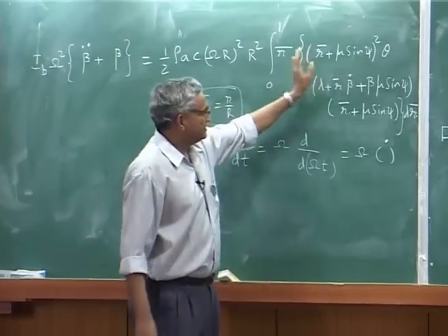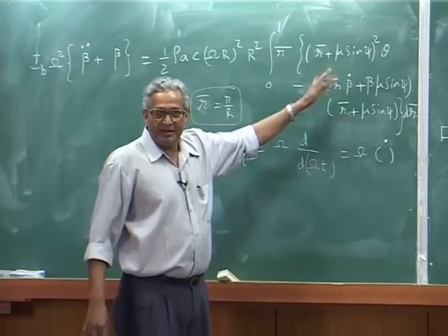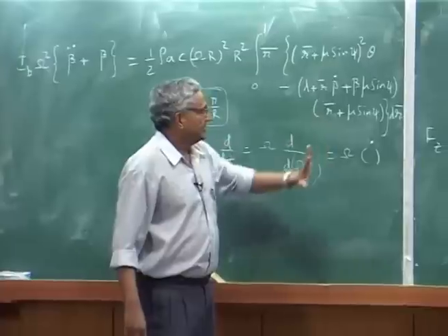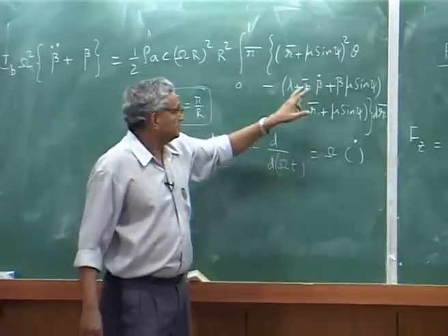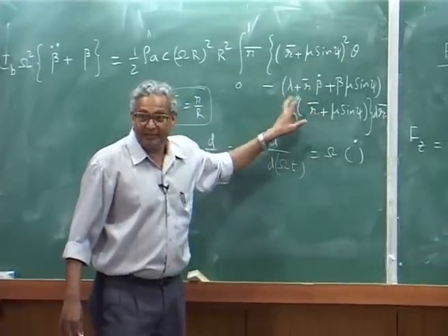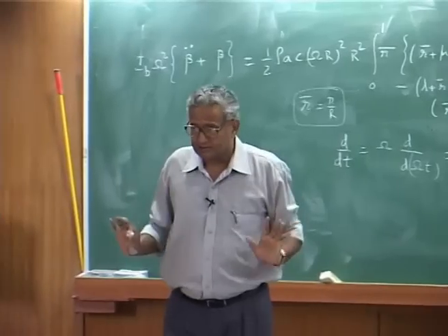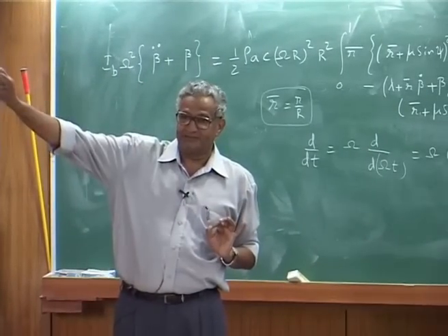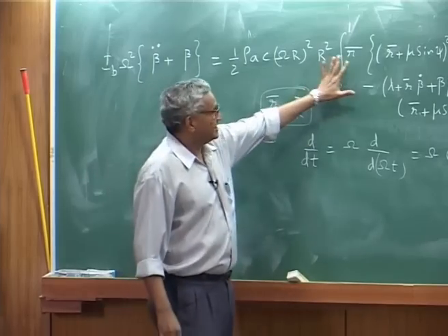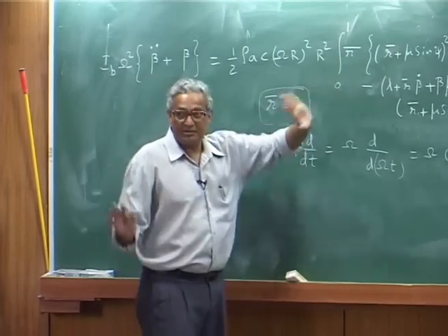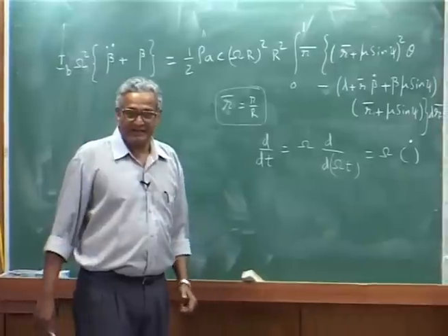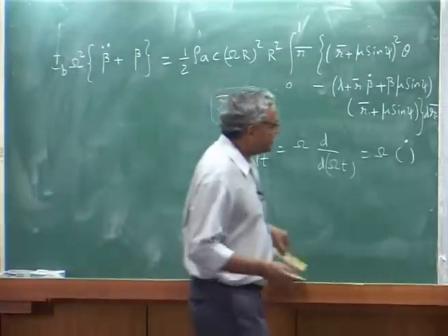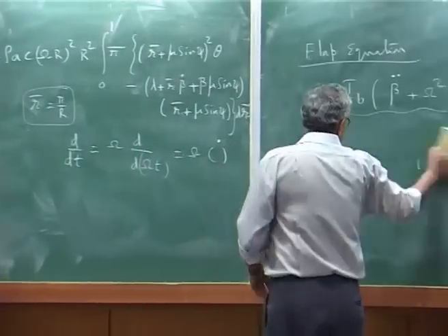So I can actually multiply everything, because mu sin psi, beta dot, lambda, assuming lambda is constant over the span, then I can integrate the entire thing for r bar separately and write the moment equation in a relatively simpler form. Okay.